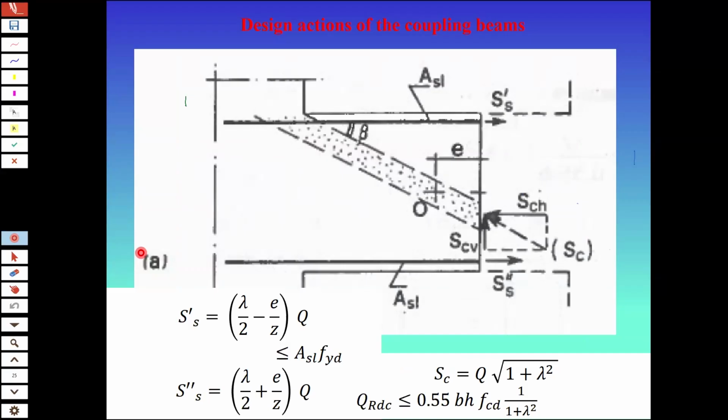Because you see, this longitudinal reinforcement, you have it anyway, so why not use it? Well, you see here the equations are exactly the same. Simply, the longitudinal forces are now in steel and the diagonal forces now in concrete. So the equations are the same because these are equilibrium forces written for the same force Q, and simply the force changes sign. But the formulas are exactly the same.